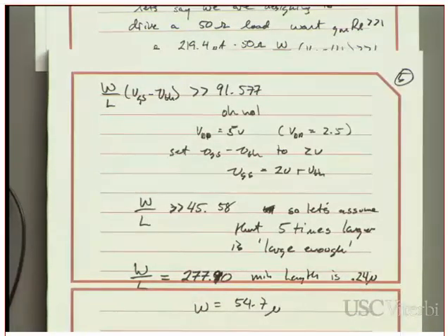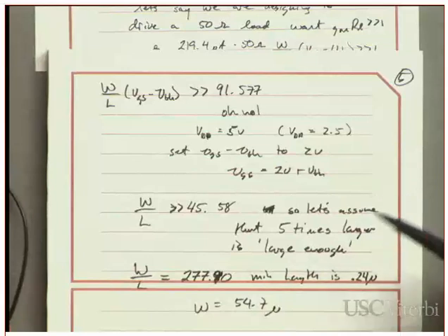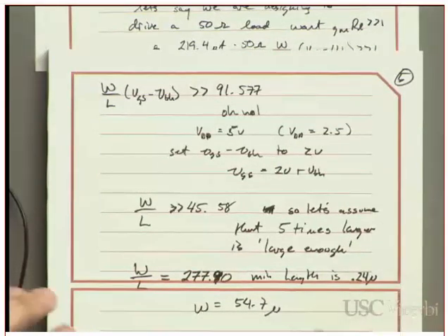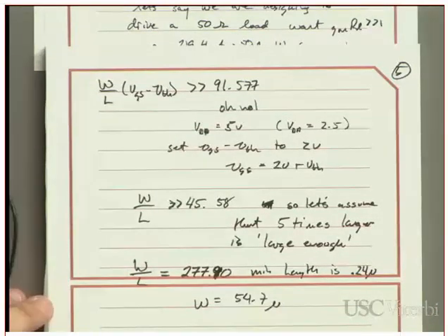So if I were going to do this, I would probably have to go back and re-examine my transfer function and see what effect the gate to drain and gate to source capacitance are actually going to have. So that's kind of where the hand analysis gets you. So what you would do then is go ahead and simulate this thing in SPICE or whatever tool you decide to use. From there, you're going to find maybe your transfer function starts dropping off as the frequency goes up.